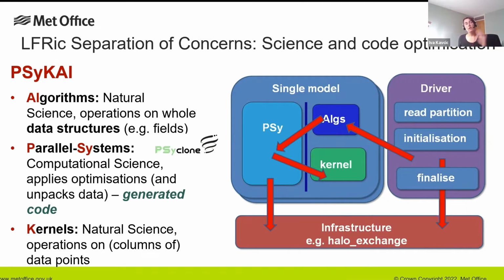To take a step back, the UM is operating on a structured mesh, so its data structures can be fully described by Fortran arrays. Because we are operating on a horizontally unstructured mesh in LFRic, we need to carry a lot of information with us: what the IDs of the mesh are on the global mesh, on the partition, the connectivities between them, the mappings, and so on.